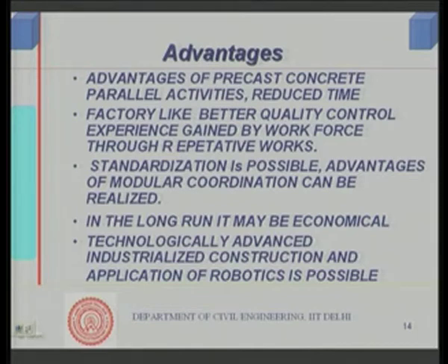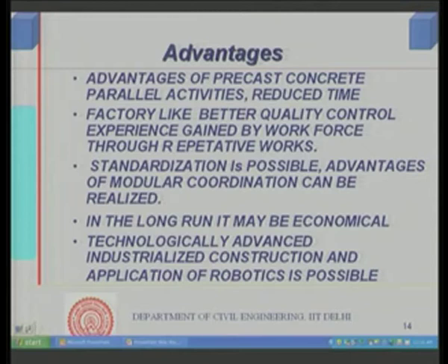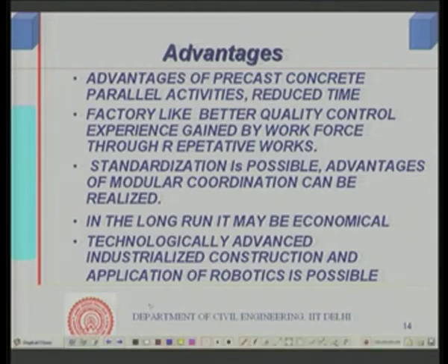Advantages of precast concrete: parallel activities, first of all. That means when you are doing the casting, let us say in case of a bridge, the deck portion, those could be beams or segments or whatever it is, you can actually construct the foundation at the same time.